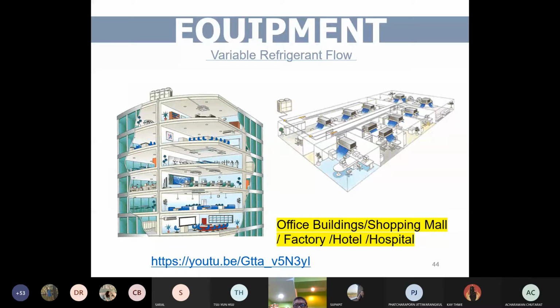So comparing to chillers, chiller is much longer. 20 years, 30 years, you can still see it running. Okay, so the VRF in the education system, like school or the university, is good, but you have to zone it. Let's say this floor, use 2-3 units on this floor, so you cannot combine.